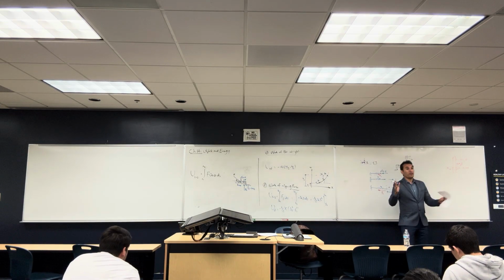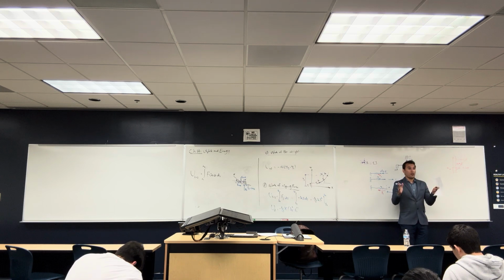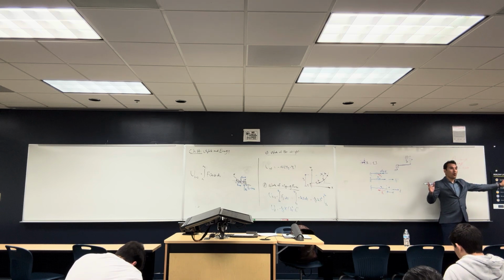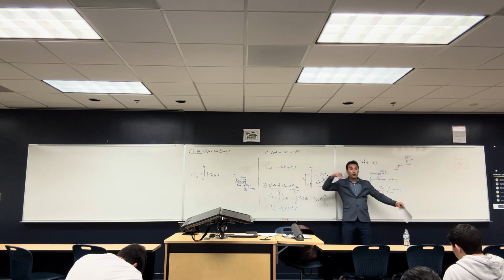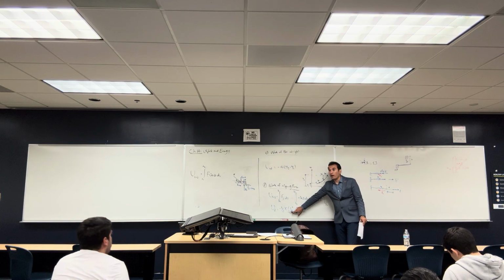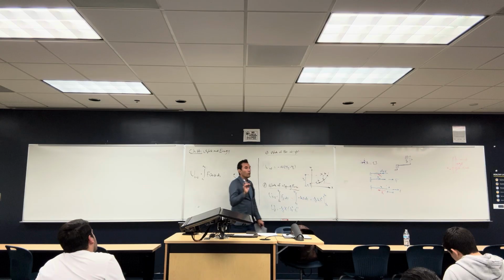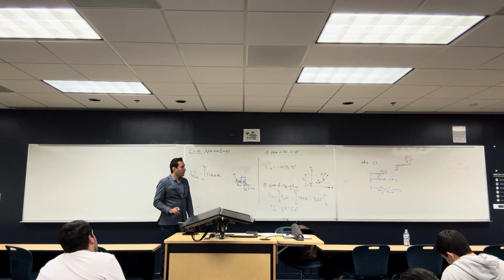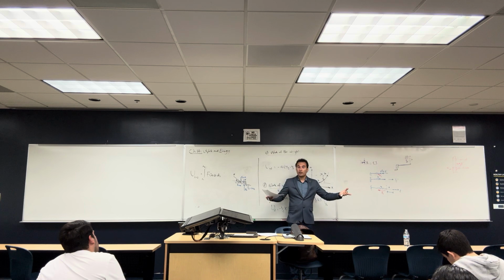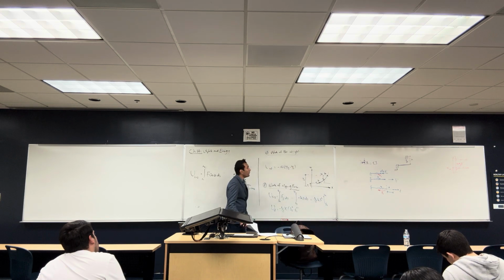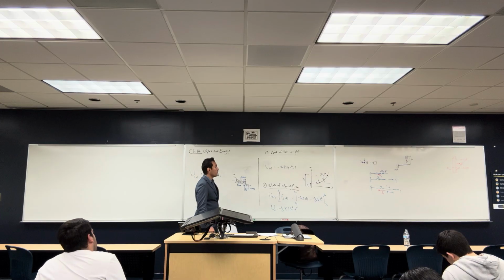Let's say that you have a spring that already stretched before the motion, and then you pulled it another 2 meters. So the initial position, which is S1, was 0.5 meter. And you pull the spring another 2 meters on top of the 0.5 meters, so the final is going to be 2.5. Okay? So S is always measured from the unstretched position. But if your spring is unstretched initially, that means S1 is equal to 0. And then you pulled it 2 meters, so the final is going to be 2 squared. So that's the final formula for the work inside a spring.